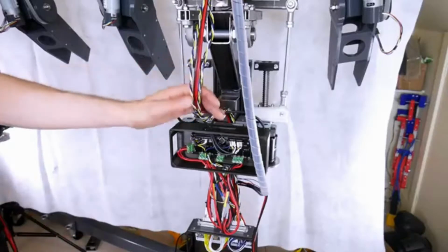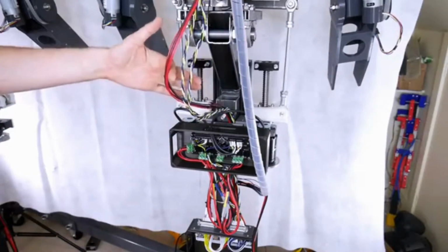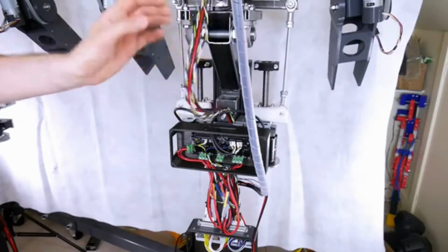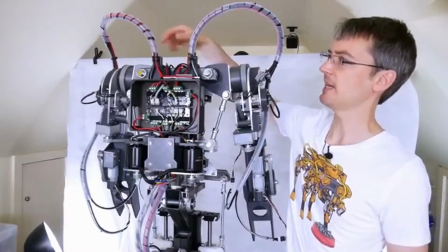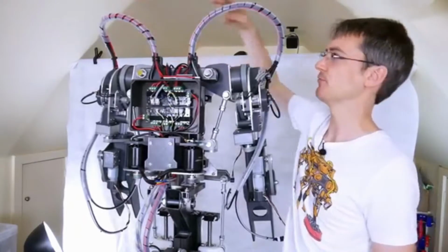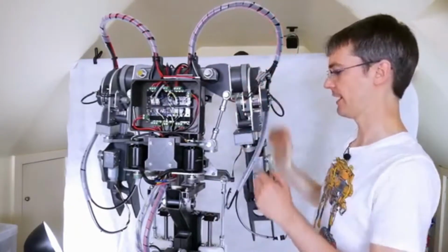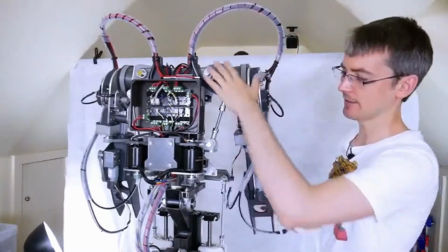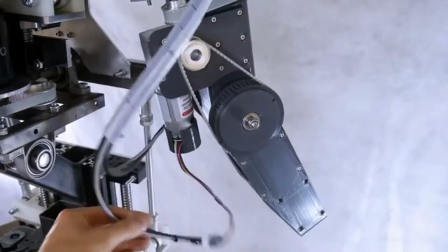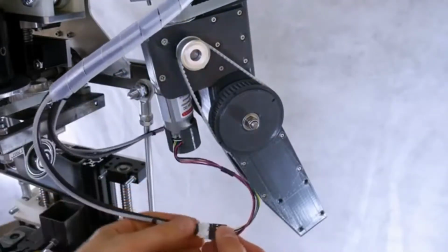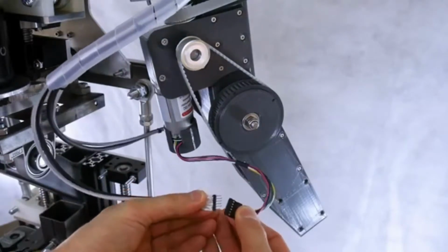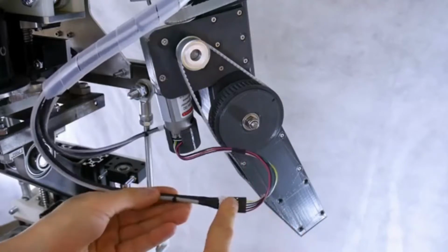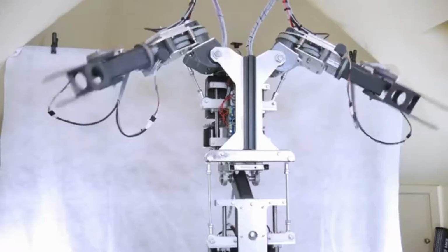So on the way up we've got this wire here, which is some power wires for the O drives and the serial grounds and resets for the two O drives at the top. We've also got this one, which is all of those encoders here, and we've got some spiral wrap that's wrapping up the cables so they're nice and constrained, and we can still move that arm all the way around with no issues there. And the sensors, they really do need sorting out because they're just hanging around. At the moment I've just soldered wires onto pin strip to make a connector, which is far from ideal. So really we need to constrain this on a PCB.